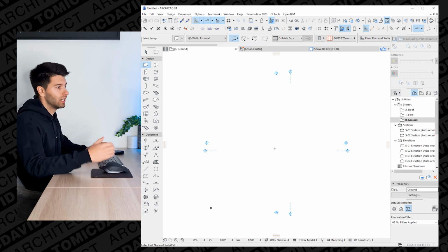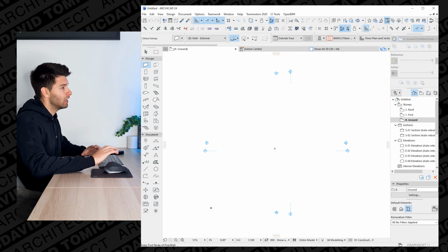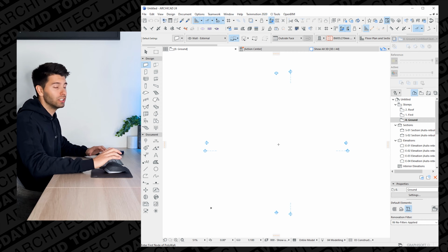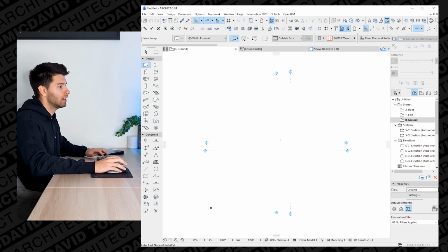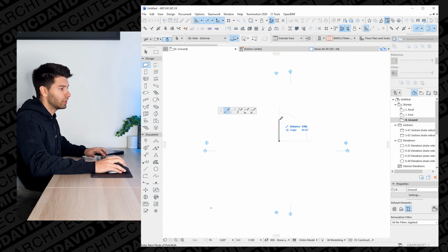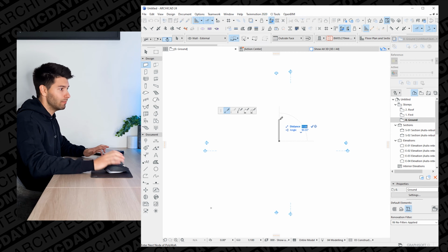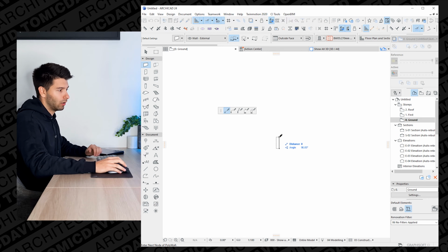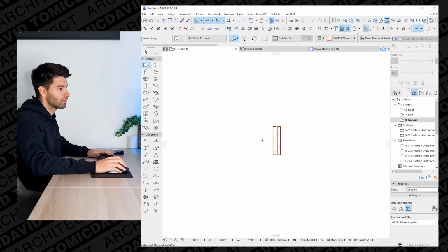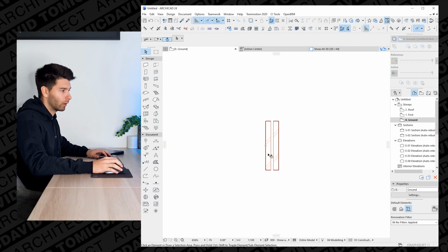So as we do a construction detail, it is a section all the way through. It isn't something that we can only draw in 2D. We like to draw it in 3D. We like to work with it and create it. So let's start by clicking once, holding the shift button, clicking the D button, and typing 1000 to draw a 1 meter long wall. I'll then click again once more to finish off that double brick wall.